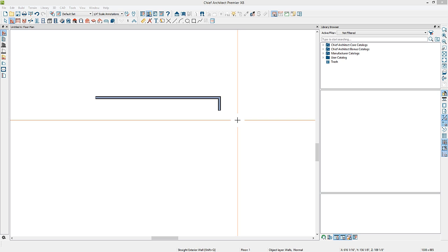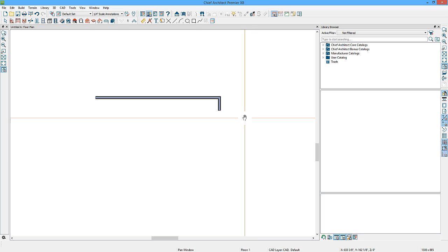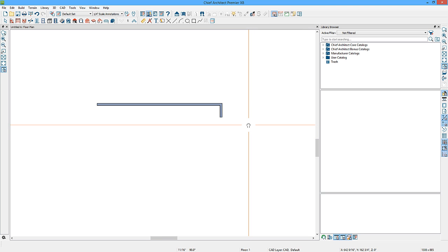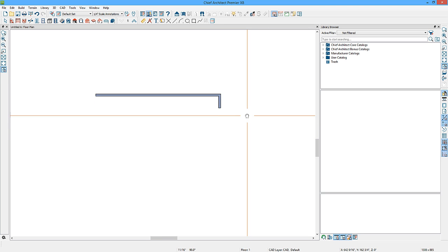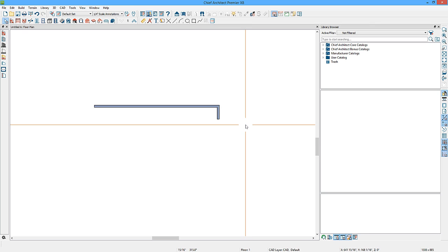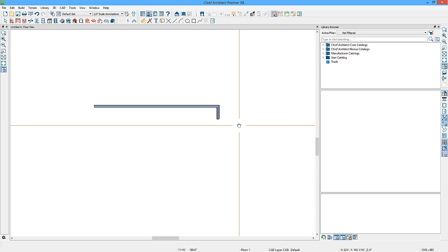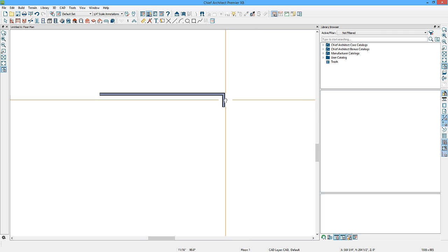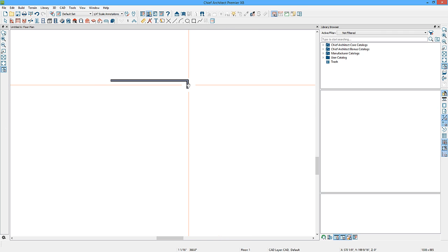And then you can pan. If you go back over to the zoom tools, the button with the little hand is your pan tool. When you activate this, you can click and drag in your screen to move the plan around in the view. Or, if you have that 2-button mouse with a roller button on the top, press the roller button instead of rolling it. Just press it down towards your desk. That will activate the pan tool as well, so that you can pan and zoom and get the plan into the right place. Then we'll go back and reactivate the wall tool.